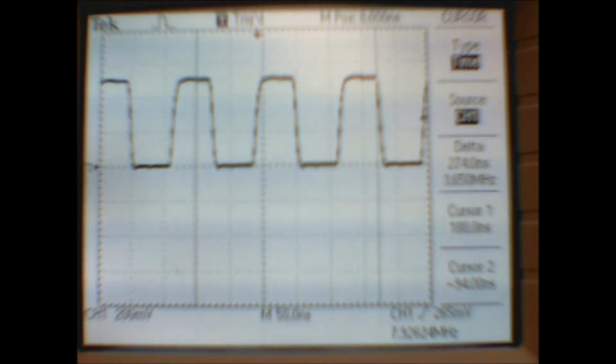So this is what the clock output looks like on the oscilloscope screen. As you can see, it's not a perfect square wave. It's a little bit rounded off. You're going to be using the oscilloscope cursors to measure the voltage, the frequency, the period, and the duty cycle of this waveform. And specifically, you're going to use those values to confirm how fast your microchip is running.